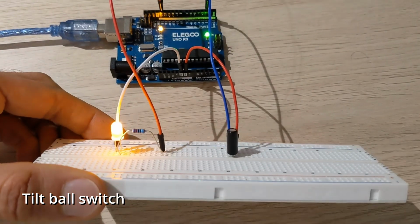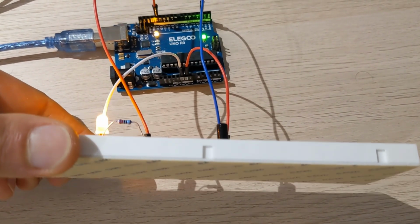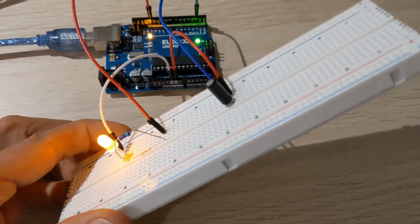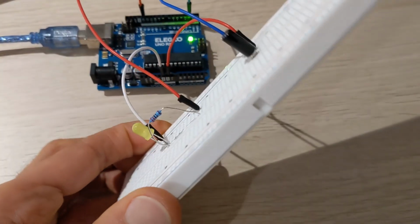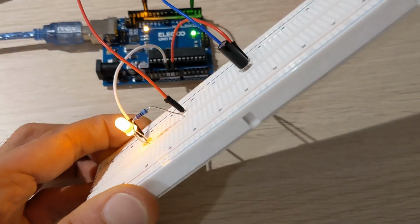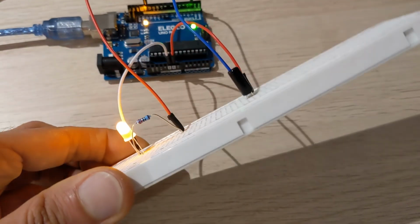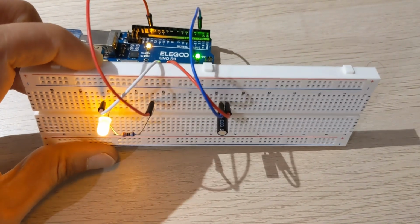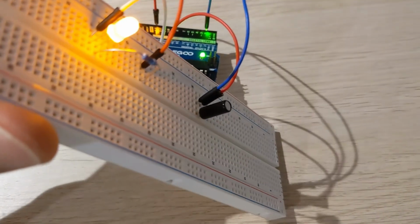The tilt bolt switch component in the middle of the board consists of a very conductive sphere that is free to move inside the component's cylindrical shape. One face of the cylinder conducts electricity and the opposite does not. And here I'm just moving the board around so that the switch captures these two different states. When the yellow LED is on, it means that we have signal from the tilt bolt switch, and it is off when the tilt bolt switch does not conduct electricity.